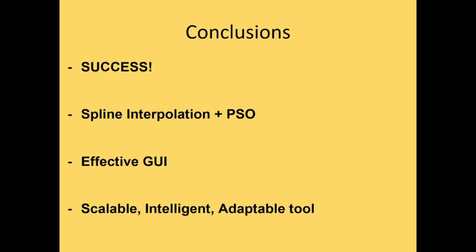So in conclusion, this project has successfully demonstrated our approach to optimizing transmission outage scheduling using particle swarm, as well as parallelism, and uses a MATLAB-based GUI for a more integrated and user-friendly experience. Through integrating automatic contingency analysis and load impact, the system lets operators make well-informed and data-driven decisions when trying to schedule a prioritized outage.